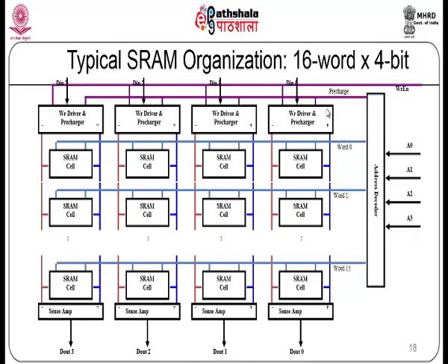So, the 4-bit data is written into that particular word. Though the write enable is applied to all the cells here, the word select signal distinguishes the word that is actually being addressed from the remaining words. Say if it is address 0000, only word 0 gets selected, the other words do not get selected. So, the information transmitted on the data lines goes only to that particular word.